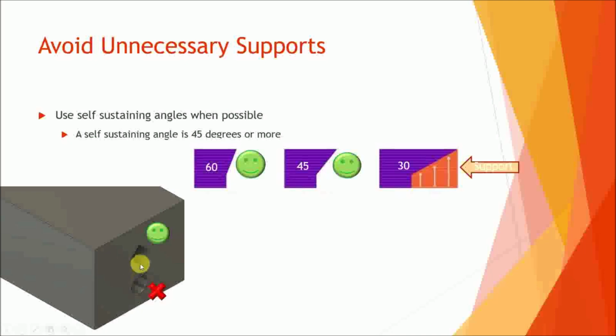So the great thing about that is you don't have to get in here and clean out all of that support material. Unlike the round hole, which would have to be supported because you have a pretty substantial overhang here at the top of the hole, and you can only reach back there so far. If it goes all the way through into the middle of the part, you won't be able to get all that support material out. So that's something to think about as well.